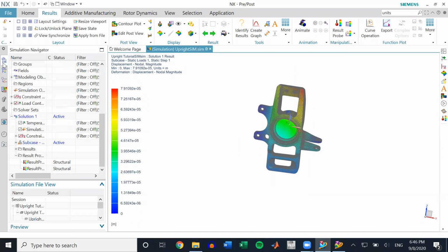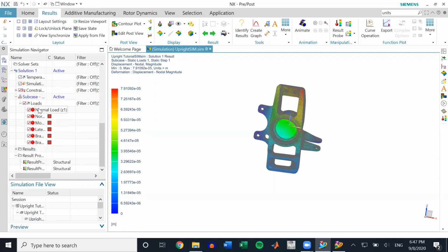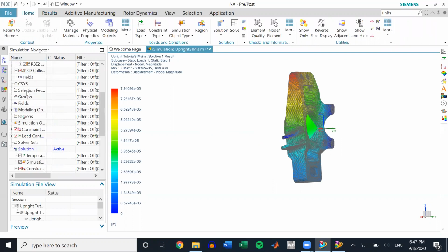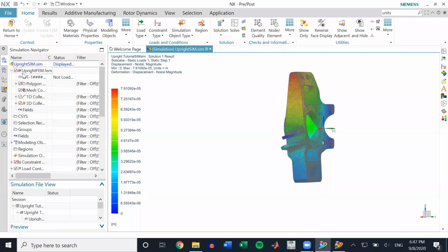And I guess one thing that I did while setting it up was I didn't just go ahead and apply all these forces and then solve and call it good. I kind of isolated each force. So basically I did one force at a time, solved it, saw how it looked, made sure that everything was as expected, and then went on, did all these different forces separately, not together, made sure they looked reasonable, and then combined them all, and then solved. So yeah, there's a lot of different ways to do it, but that's the basic workflow.